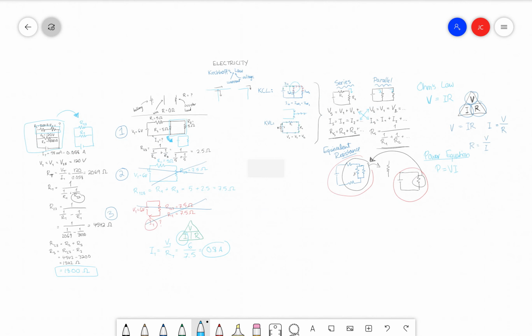Whew. This was a long video. There was a lot we covered here. We looked at Kirchhoff's current and voltage laws, series and parallel circuits and their formulas, equivalent resistance, Ohm's law, the power equation, and then we went through some examples of circuit analysis. Hopefully this has served as a comprehensive video detailing all about electricity.